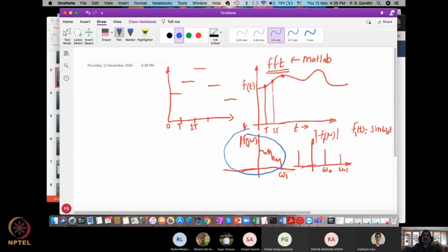So you can get this kind of a signal, and typically all the signals that we consider in the mechanical domain will have some kind of a limit with this omega 1 here. So you'll have signals which are limited in frequency. You cannot have a signal having infinitely many frequency contents. Frequency contents will be limited by a certain higher frequency, because mechanical elements in the system cannot move faster than a certain speed. So this is what we will consider mostly for signal analysis, that our signal is band limited. It's called band limited, in terms of jargon.